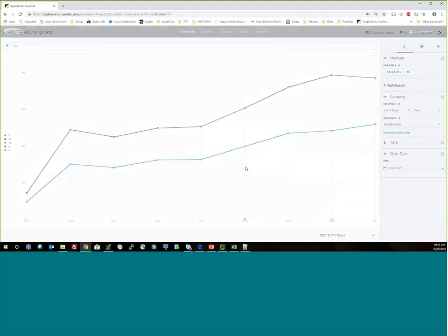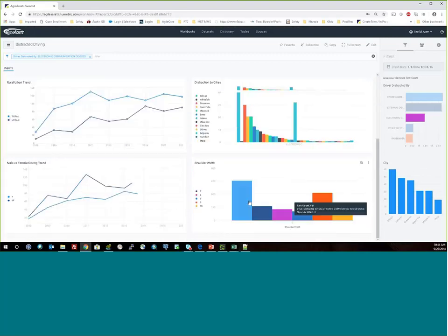Okay. The other thing we can also do in this, we can also consider some of the geometric aspects of that. So I consider the roadway shoulder width. I'm trying to identify if I'm getting distracted by cell phone, whether having a better shoulder width will help me reduce the crash or not.